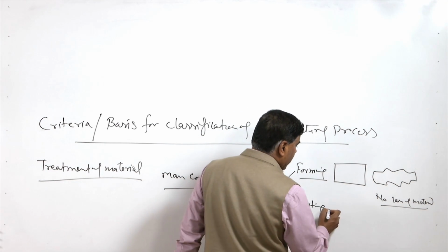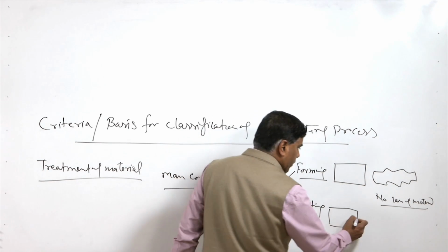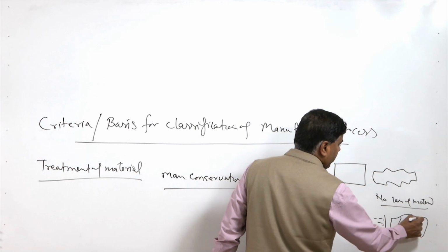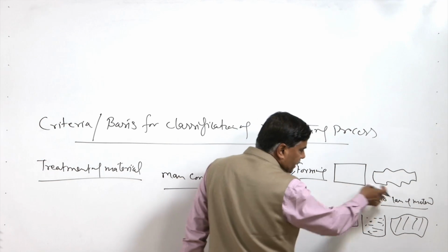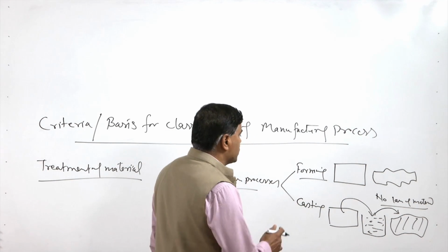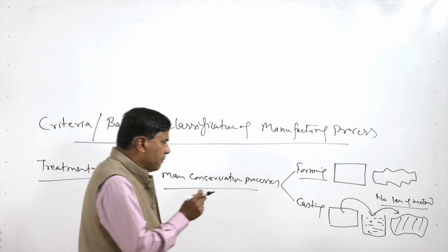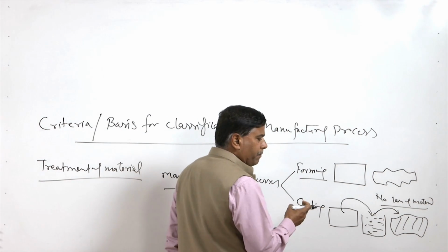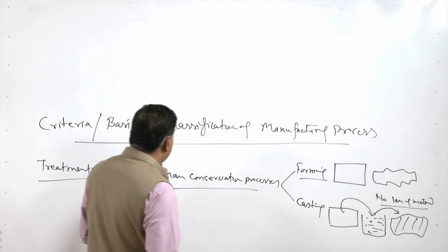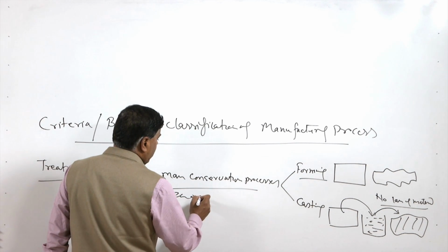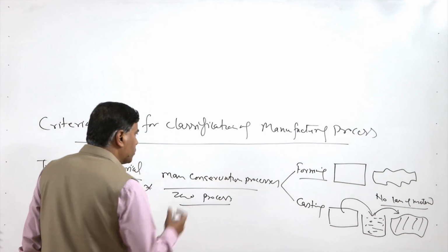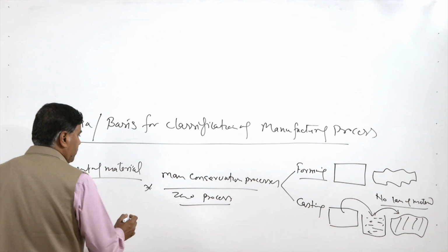Similarly, in case of casting, we take one amount of the raw material and then it is brought to the molten state, and then the same is poured into the mold to get the desired shape of the component. So, the product that we get, only its shape is changed from the initial raw material. It is converted into molten metal and then put into the mold, and the desired shape is achieved. So, technically there is no loss, however little loss may be involved, that material is getting lost in the form of slag or impurities or oxidation, but those losses are very negligible. That is why forming and casting, both these processes are put under the mass conservation or zero waste processes, because there is no loss of the material, only the shifting of the material takes place from one region to another using two different approaches. In one case the force is applied, and in another case the material is brought to the molten state.